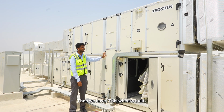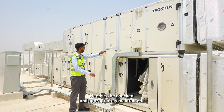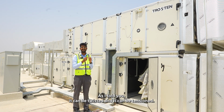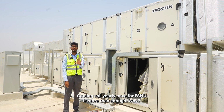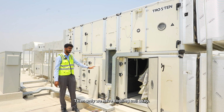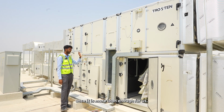Then this wheel's belt tension also needs to be checked and appropriately maintained. This is the wheel belt, so this needs to be tensioned. As I told you, it can be twisted and it can be tensioned. For the cooling coil, once a year for the FAHU is more than enough. Why? Because we have 3 primary components: 2 filters and the enthalpy wheel, and only then the cooling coil. So if the filters and wheel are maintained regularly, once a year is more than enough for us.